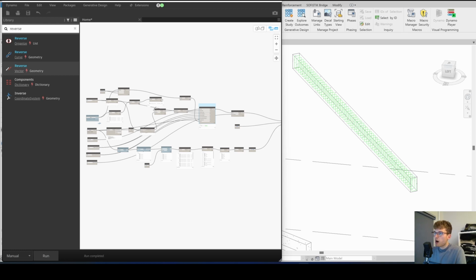But for now you saw how you can use the Dynamo geometry, make your own geometry out of it, in this specific case make stirrup geometry out of it, and then bring it back into Revit and actually create elements. I hope this tutorial was useful and is helping the community. As I already said at the end of the demonstration video, the next tutorial will be about the longitudinal rebars in beams, and after that there will be a tutorial about the automation of rebars of beams.